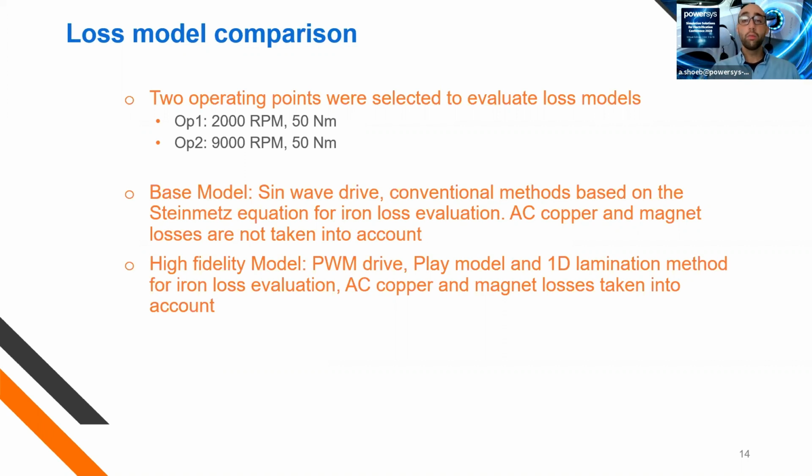For my high fidelity model, I'm using the equivalent circuit method. I'm using a PWM drive. I'm using the play model and 1D lamination method to calculate for iron loss evaluation. AC copper losses and magnet losses are taken into account.